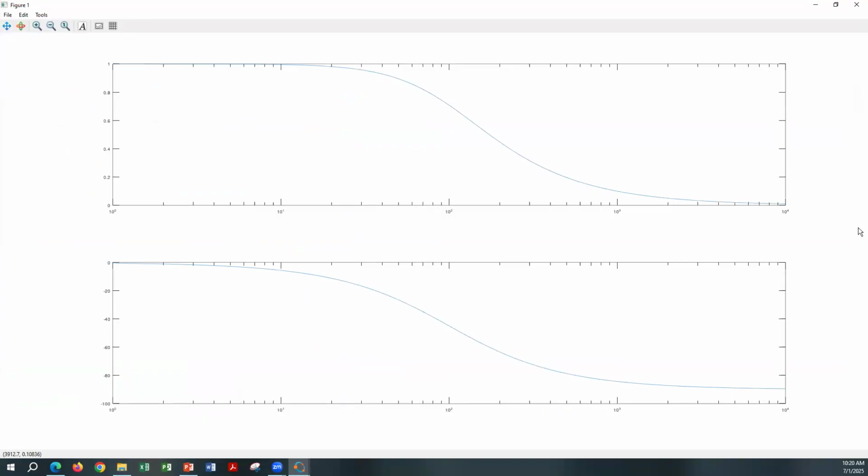So with the semi-log, that is the x-axis in the logarithmic scale, as you can see, going from 1 to 10, the same length of frequencies as from 10 to 100, 100 to 1000, and 1000 to 10,000. So once you divide the x-axis into equal scale, equal range, then no matter in which section of the frequencies the activity is happening, you can clearly see that in the low side of the spectrum you have the activity happening, and then finally it dies down, starts going towards 0. It's not 0 yet, but it starts going towards 0.